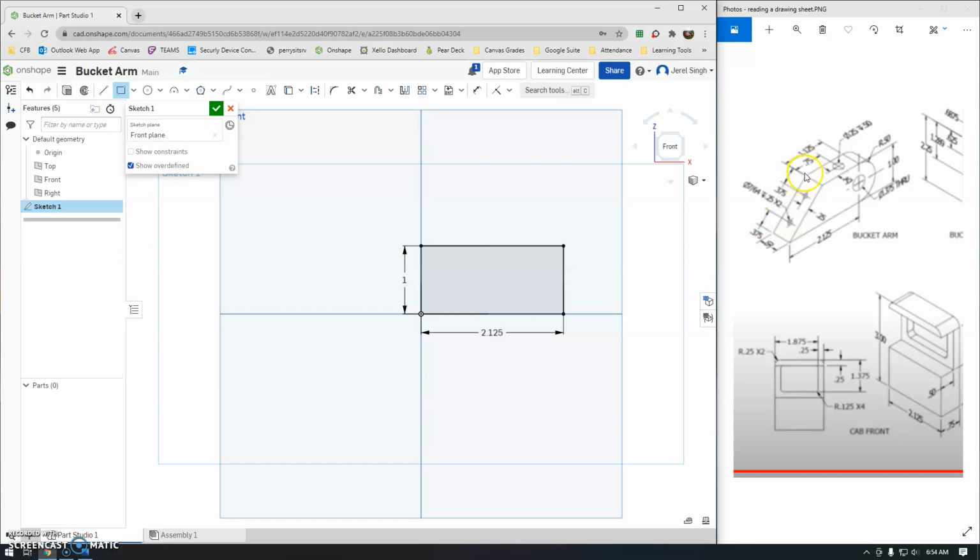One thing that we are given is the distance of the top side before it starts slanting diagonally. So I'm going to use this information, select the line tool, start from the lower left corner, and I'm going to draw this. Now, specifically, do I know the length of this hypotenuse to this triangle? Not currently. So I'm going to place this anywhere on the line, except in this center square. I don't want to constrain my line, or else I'll have trouble dimensioning it later.